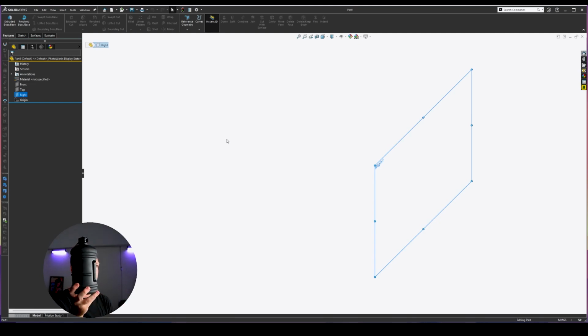Example, here, if I was doing this sketch, okay, then what I'm doing is sketching this side shape to the bottom, and there would be a line that goes straight up the middle. That would be my construction line and center line. And it would revolve like this when it's in 3D. I don't want to sketch it like this on the side, because then in all my drawings, all my part models, everything, facing the wrong way. So you must start with a plane whenever you're starting a new file.